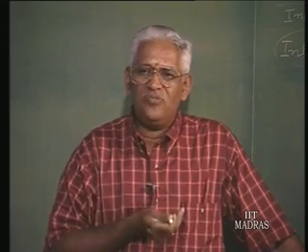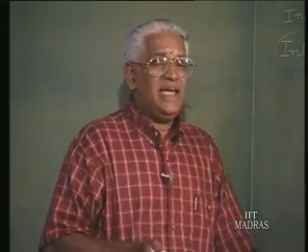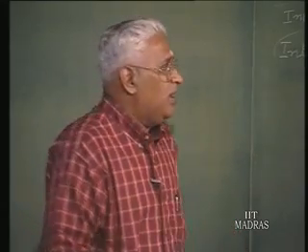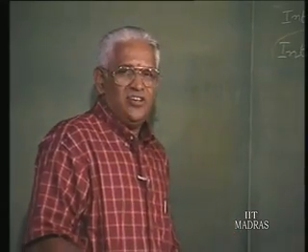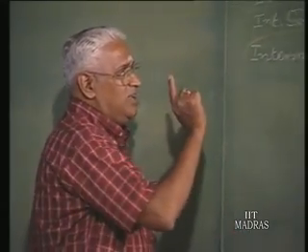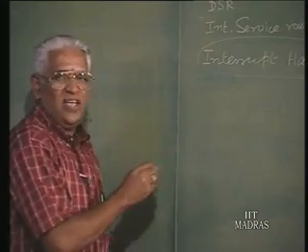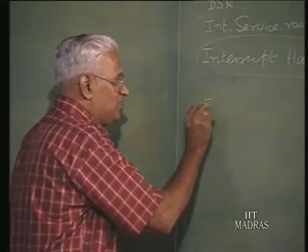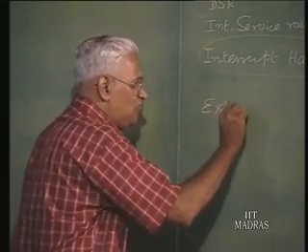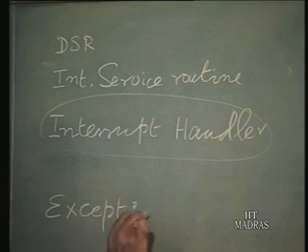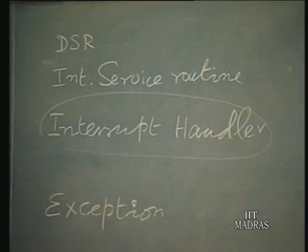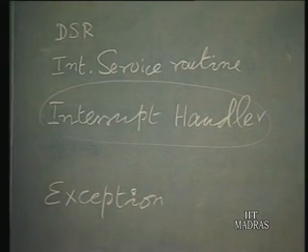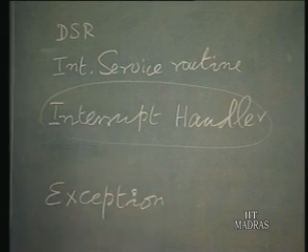Or in division, if divide by 0 comes, the processor cannot proceed. So, the processor may get interrupted, and in general a flag such as an exception flag is raised. That is, an exception has arisen and the processor has to respond to it. It is similar to the interrupt.